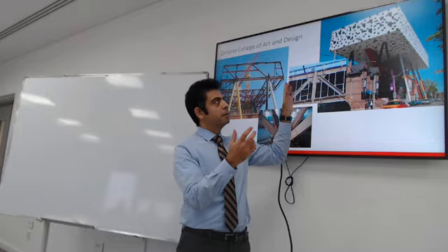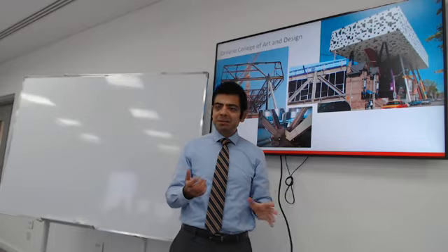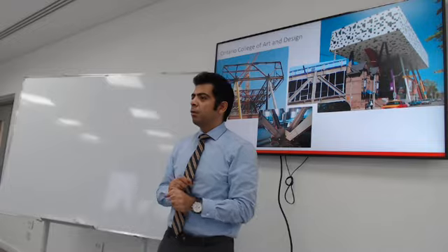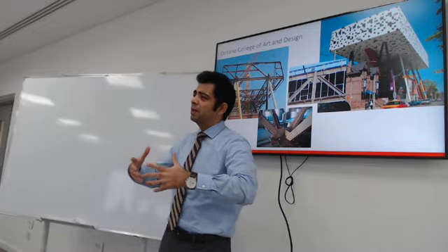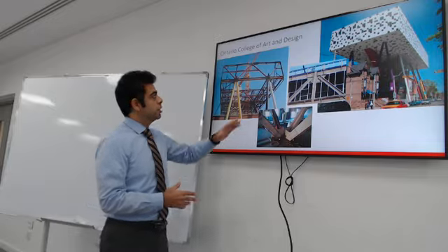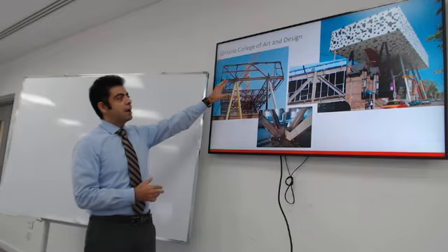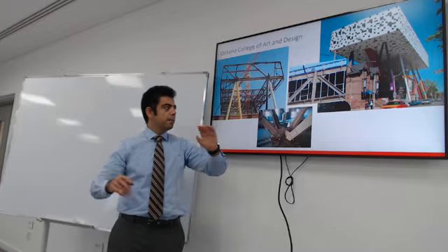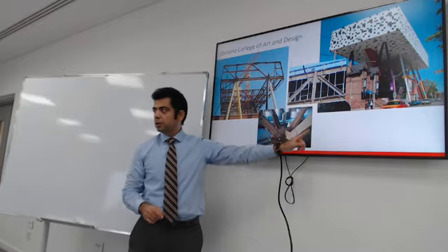When you get very interesting and crazy types of architecture like that, steel is usually a good application. If you want to build it from concrete, it's going to be bulky, very heavy. It's not going to give you that interesting look. So during construction, this is what happens. You need a tower crane to pick up the pieces, line them up, and this is how the connections look.